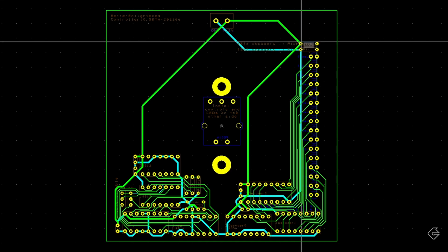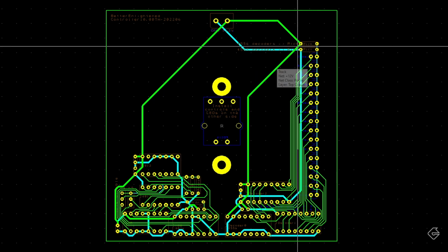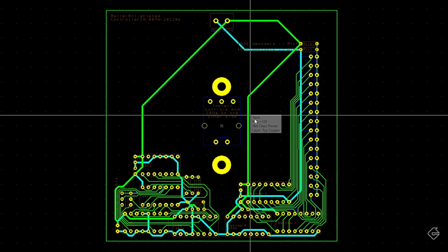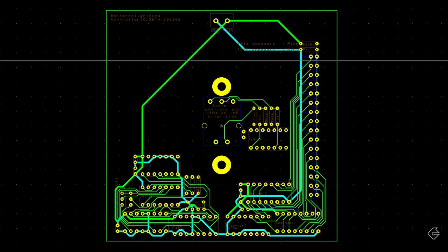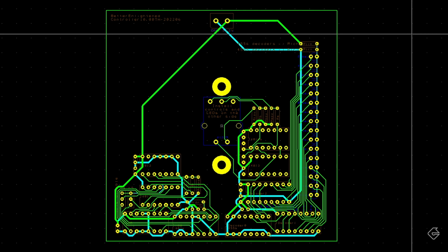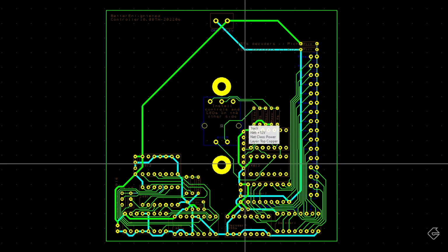The first thing I'm going to do is remove this plus 12 volt line because this is kind of in the way. What I want to do is start populating some of our components over here. There's our resistors and they're wired up accordingly. Let's continue. I'm going to add in that 40106 chip and wire that up. Finally, we're putting in our plus 12 volt connections and you can see the nice thick trace that I've added in to get the 12 volt connector.